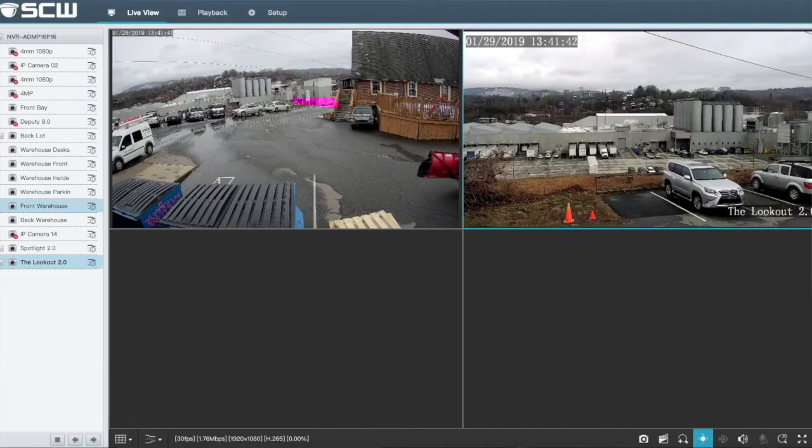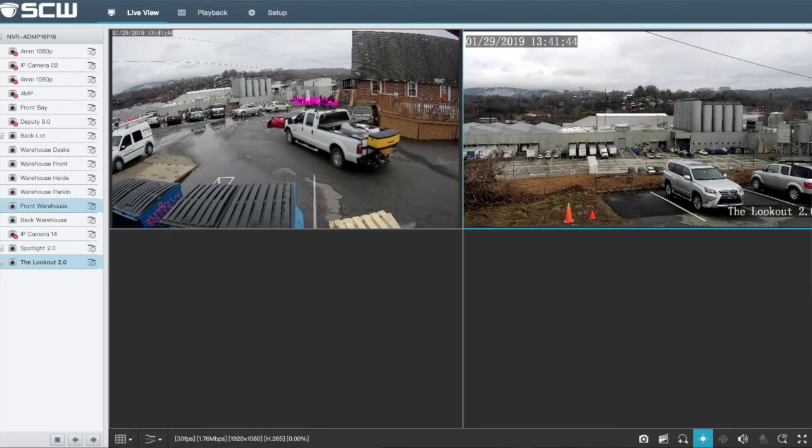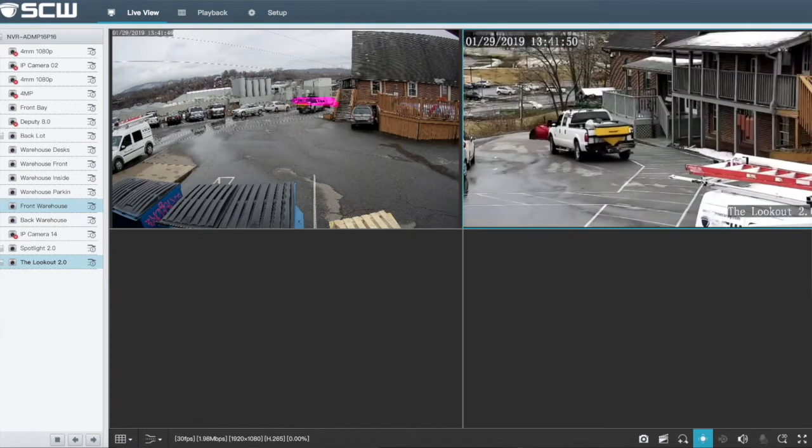To give a real world example where you've used this, we go back and we mentioned that PTZs are only seeing what they're seeing. You can't go back on playback. So, we have a front entrance, a pretty narrow front entrance. In this case, the PTZ was looking towards the right. And we had a camera that's looking at the front entrance with a line crossing set up. Once that vehicle crosses that line, the PTZ knows, we set up a preset on that PTZ. Once that line's crossed, it goes to that preset, and it's able to zoom in and get a better look at the vehicle coming out or going in.